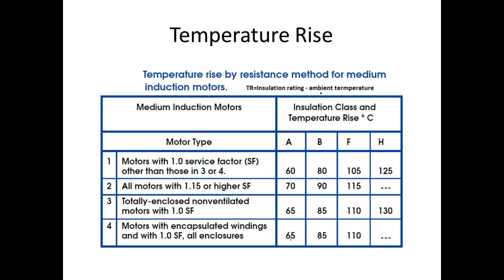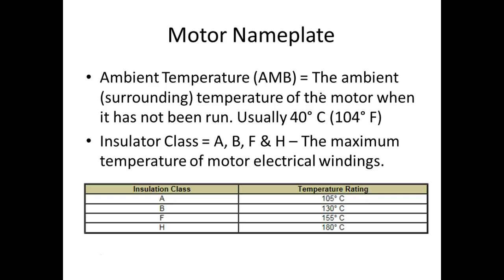If you've got that very thin insulation on there, and it keeps touching like that, it could eventually short some windings out. So a lot of times they'll take that stator and dip it in a lacquer or varnish type of thing to keep those windings from vibrating. A lot of transformers do that. So this is just temperature rise. This could be on the motor. Well, what else could be on there?